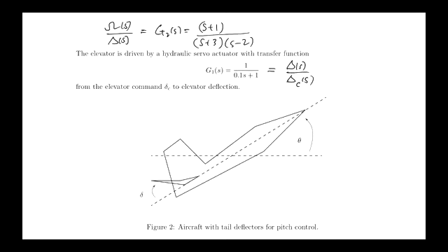Right? So there's a little feedback control loop that determines what this angle should be on the basis of a reference for the pitch rate. And then the pilot is like a control loop around that that looks at what's going on. That's the measurement that the pilot takes. And then the pilot sets the command for the pitch rate reference. Okay? So it's like a cascade of control loops, one of the control loops being a human pilot. Okay?